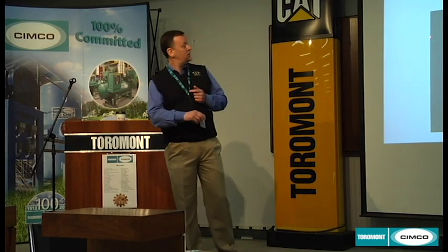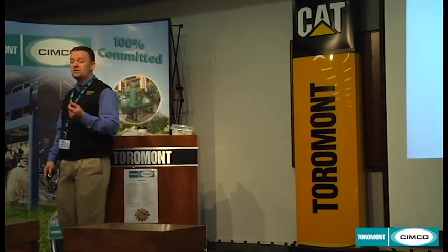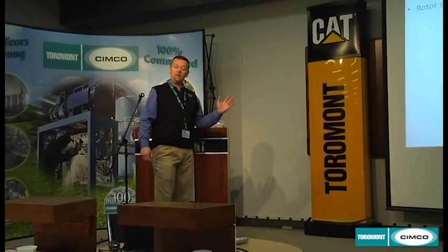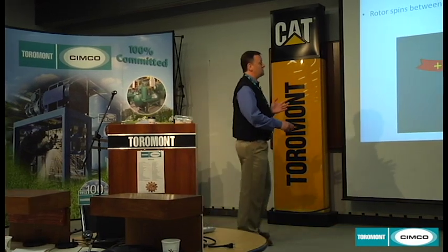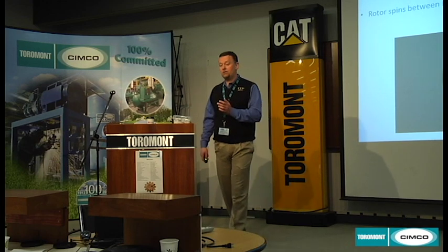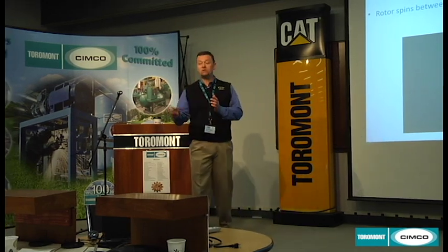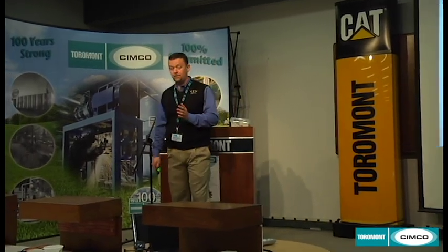And what we do with air is we take a heat source, which I think is going to show up over here in a minute. We heat it up to about 250 to 280 degrees. The air is then passed through the rotor in a counterflow direction. The moisture that was absorbed in the process is now given up to this warm air, and we can reject that away from our control environment. And in this way, the rotor is continuously regenerated, and the process is a continuous process.